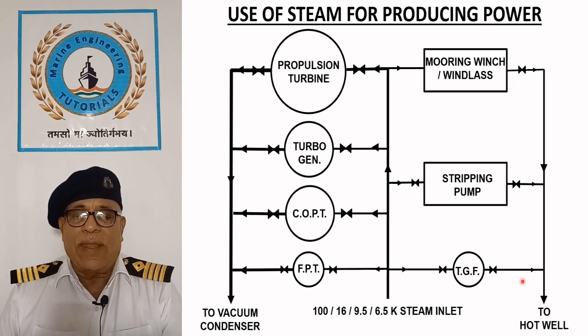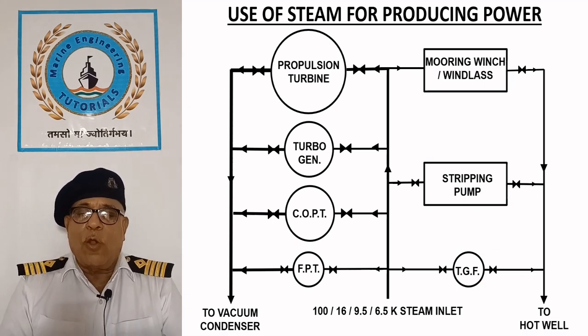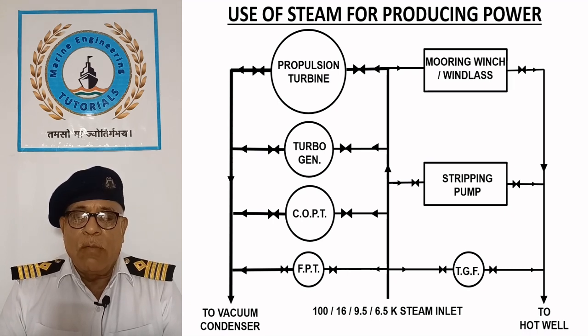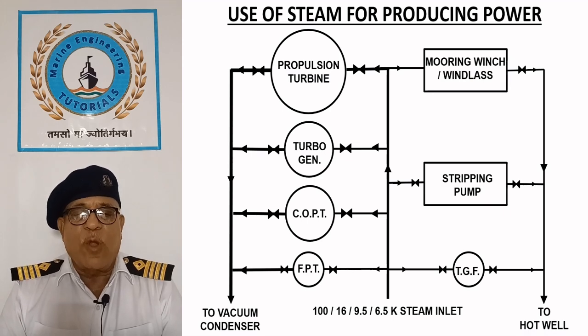Turbo gas fan. On conventional oil tankers, a steam turbine driven fan may also be used for gas freeing the cargo tanks. These are especially suitable for operation in hazardous tank deck atmosphere and typically operate at 9.5 bar steam.